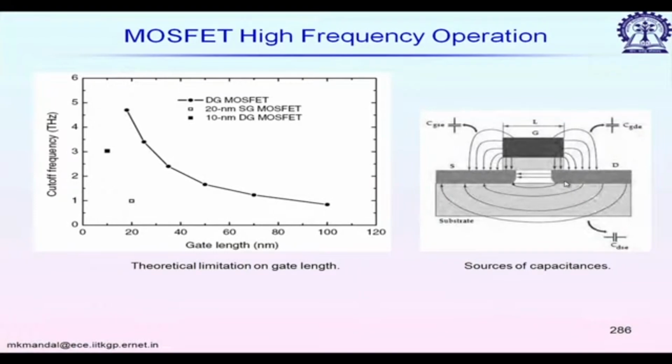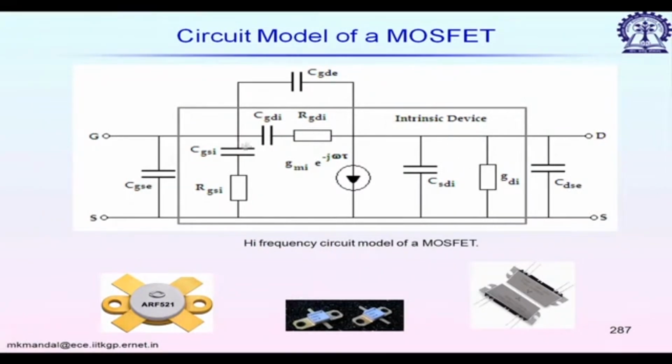And in addition to that, we have body effect. So, in the equivalent circuit for high frequency operation, we have to add all these capacitors, one between gate and source, one between gate and drain. The capacitors and resistors inside the rectangular box show the intrinsic device property. In addition to that, due to packaging and other effects, we have some additional capacitors, and that is sometimes called the extrinsic model of the device.